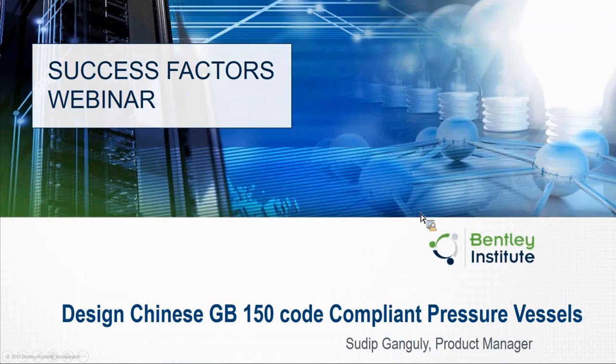There is a question on supports. What type of supports can be designed using the product? So like I was showing in AutoPIPE Vessel, you have a total of 16 templates, which are actually the various configurations of pressure vessels that you can conceive of designing. So you can design horizontal vessels, which are saddle supported obviously, and you can design various types of saddles, up to 10 saddles. You can design vertical vessels which are skirt supported, leg supported, as well as internal ring or support lugs.